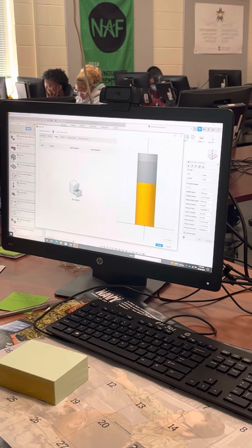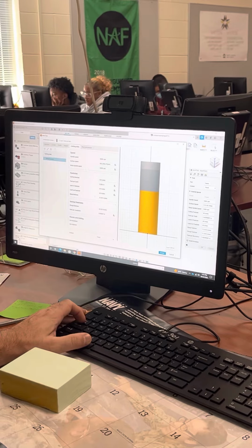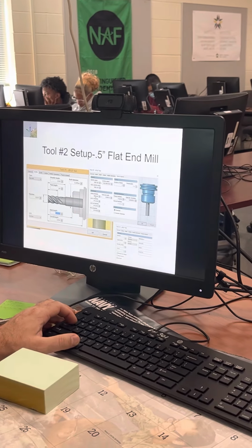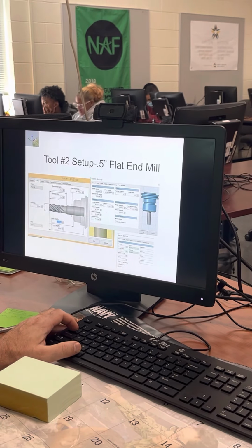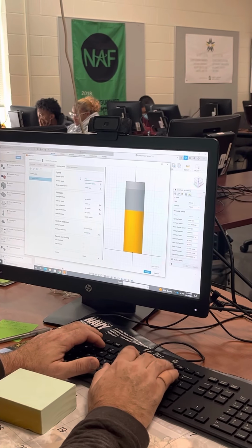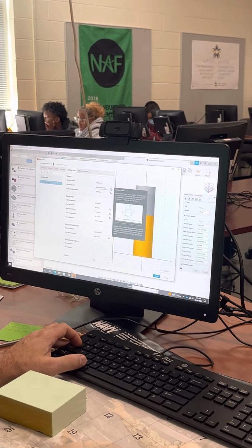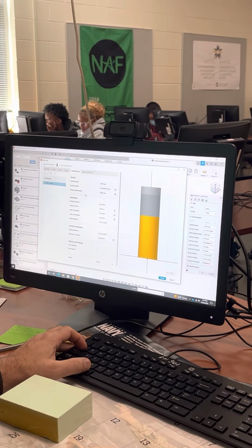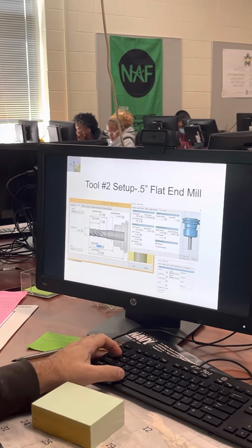And then we'll look at the cutting data. So these are like the speeds and feeds. So we recommended 40 inches per minute last time. So we're going to maintain that, 40 inches per minute, 4,000 spindle speed. So we'll back this down to 4,000 RPMs. Surface speed is a function, so you don't have to calculate that because it's already in the library. Ramp spindle speed, that's fine, we'll leave that. So we're just going to match this recommended data up.